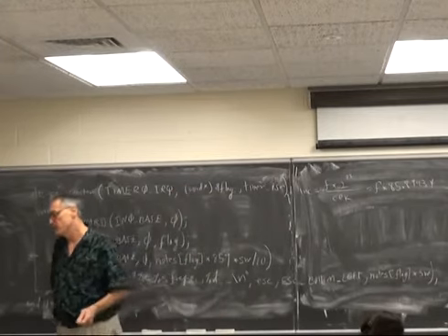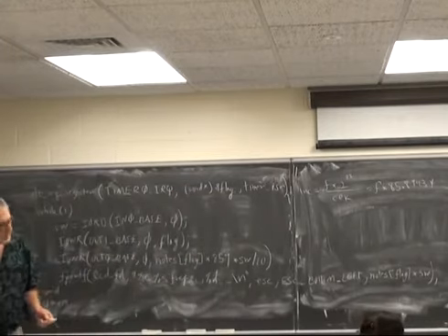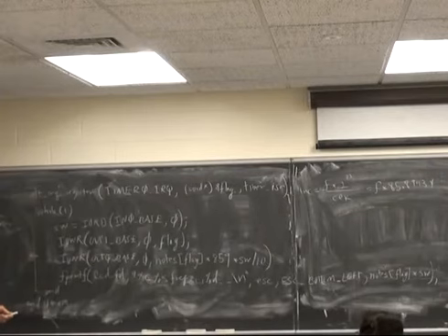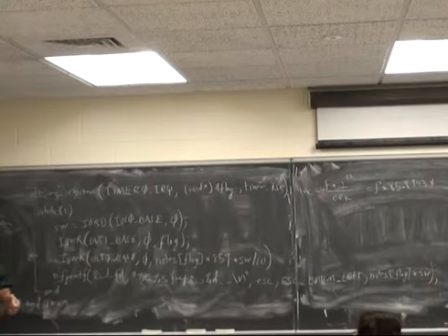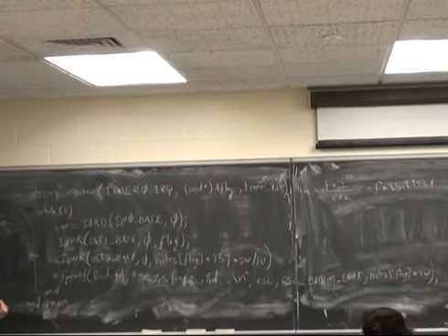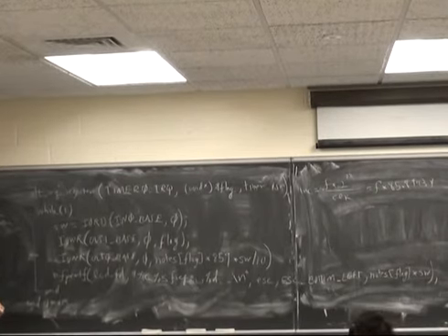So it's probably going to print between 10 and 12 characters, so it's going to take 10 or 15 milliseconds to execute this. It's not a very fast thing to do. Don't ever put an fprintf in an interrupt service routine. It will kill it.